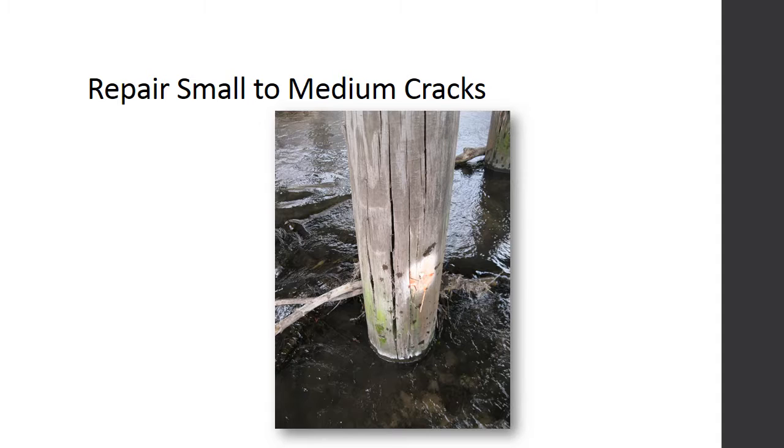Small to medium cracks and splits caused by weathering or shrinkage create pathways for decay fungi to enter the untreated wood at the core of the timber pile. Therefore, consideration should be given to regularly repairing cracks and splits. Epoxy grout can be injected under pressure for filling checks and splits. The epoxy seals the affected area, preventing water and other debris from entering. It can also restore the bond between separated sections, increase shear capacity, and reduce further splitting. Another method involves injecting low viscosity epoxy to fill the void, then sealing using a sealing epoxy.